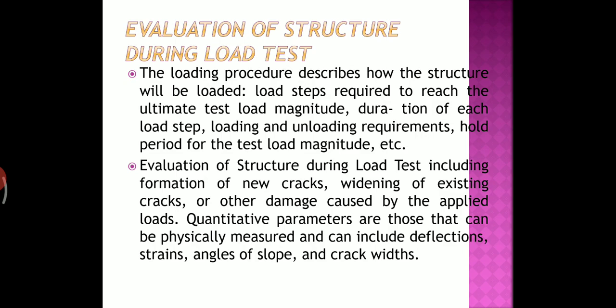Then the evaluation of structure during load test. So what are the things that we are going to evaluate? Before that, the loading procedure describes how the structure will be loaded: the load steps required to reach the ultimate test load magnitude, the duration of each load step, loading and unloading requirements, and the hold period, that is, for a particular magnitude of load, how long it will be held in the load test. So all these things are to be clearly predetermined in the load test.